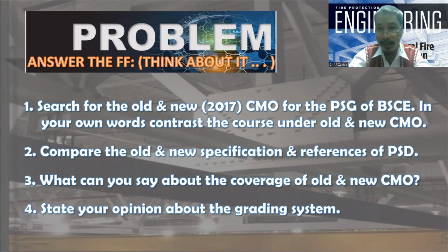So, for example, in design, we don't have the dimension. We have the material and we have the specification of the material: the stress allowed by the material, the allowable stress that the material can handle. We know it because we know the material. We can use that allowable stress in our computation and find out the dimension. That is the design.